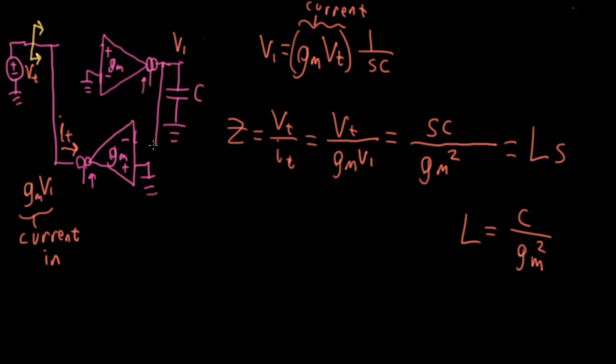In a PCB level design, we might want to throw in some resistors here to make sure that we don't have too much voltage going into the OTAs, to make sure the OTAs stay in their linear range. So let me put a resistor divider down here and one up here. And to avoid having current going through here, we should also put some buffers here.